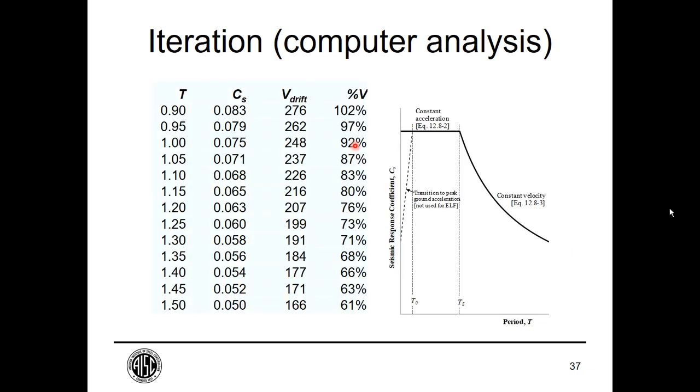If we're doing it, say, the old-fashioned way, where we compute the period, get the drift, and then calculate the displacement, at the beginning, our CuTa for this system, our approximate period times that Cu factor, put us at about a period of 0.9, which gave us a certain base shear coefficient. And then we would apply that force, calculate our drift, find that we were perhaps significantly below the drift limit, and select more flexible members, calculate a new period which was longer with a lower force, and so on.